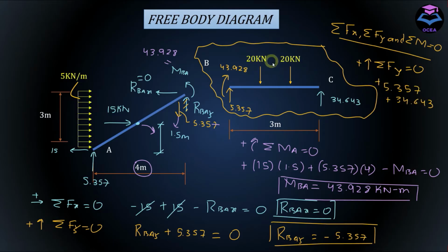And 220 kilonewton loads going downward. And this tells you that member BC is in equilibrium and your calculations are correct regarding the vertical forces. Similarly, you can check summation of f of x and summation of moment about a particular point, and this would also equate to 0. If it's equal to 0, it means that your calculation regarding horizontal force and the moment is also correct. If it's not, you need to check your calculations here.